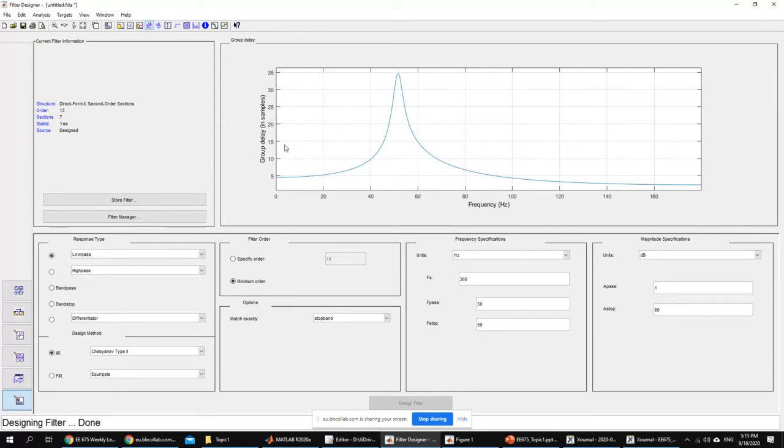If you have an FIR, it's going to look flat, which is definitely an advantage of FIR filters, but as we saw before, FIR has a really bad disadvantage in that the order of the filters produced by FIR design is much higher than those produced by IIR design.